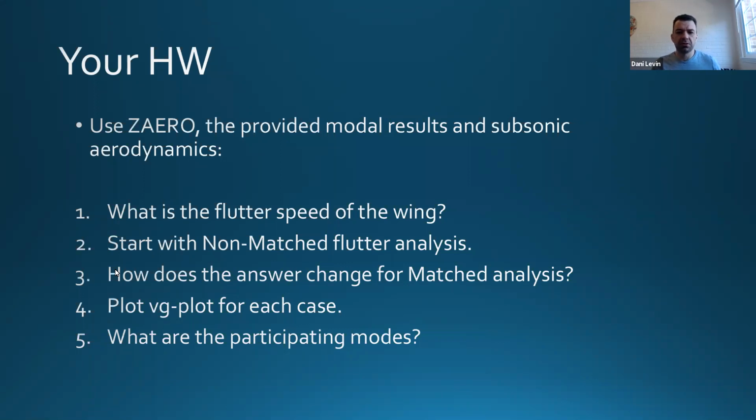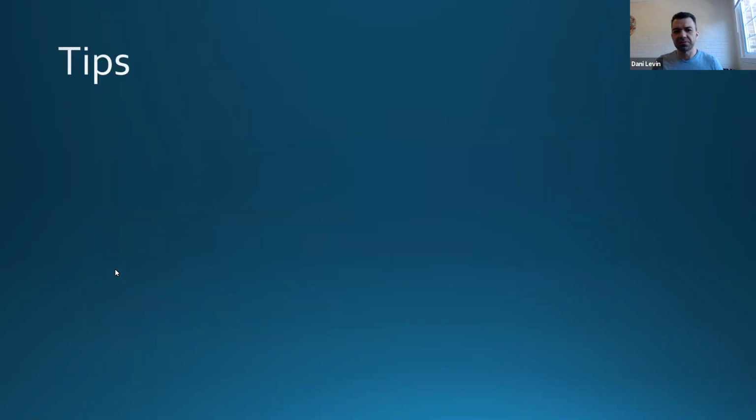From what I heard in industry, there are several practices. At Airbus, I believe they include all of the modes up to 50 hertz, for big aircraft, and this can be hundreds of modes. For another approach, I heard they use the first 120 modes. So it's a mixed answer. Okay, guys, several tips.